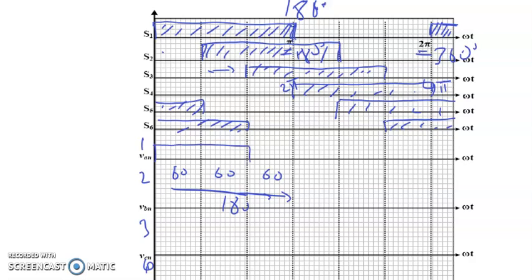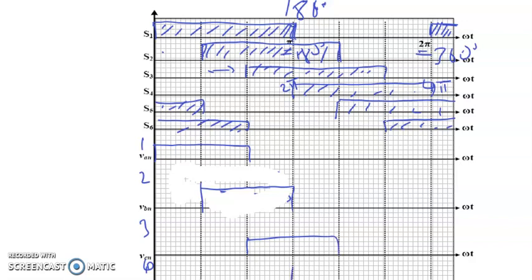and off. And then for switch number 2, it starts after a 60 degrees gap and conducts for 120 degrees. Switch number 3, like that. Switch number 4, like that, 120 degrees. So it starts again to conduct on another cycle. It means that if we have only one cycle here, it just ends here.